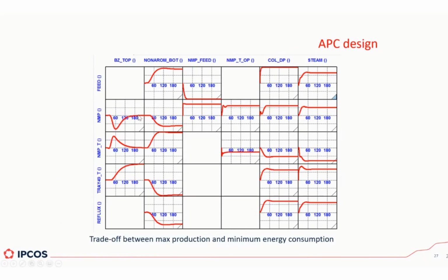in that case, you cannot use either the reflux or the solvent to try and control the top quality. And you say, oh, what? So you see, it's already getting counterintuitive. To control the top, you use the steam in the bottom. And obviously, to control the bottom, what do you need to use?